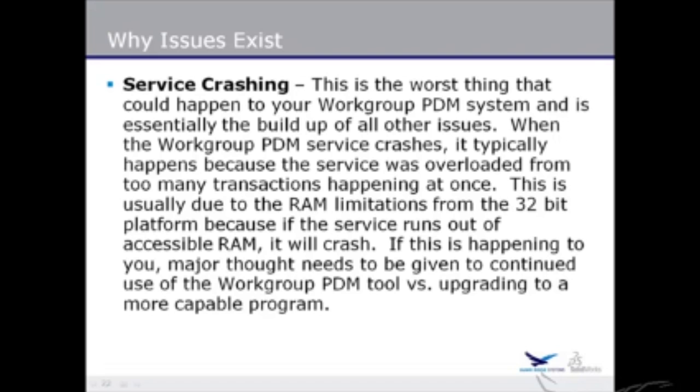In our customer base, we have seen performance issues start when your Vault data folder is 60 gigs. We've seen performance issues not start until your Vault data folder turns into 100 gigs. So you're really just going to have to monitor it and talk to the users to see when these things are happening, because there's just not a tool that we can use to assess that.